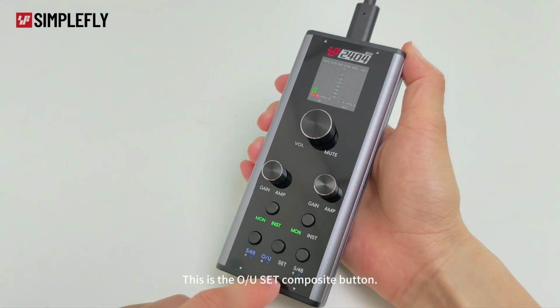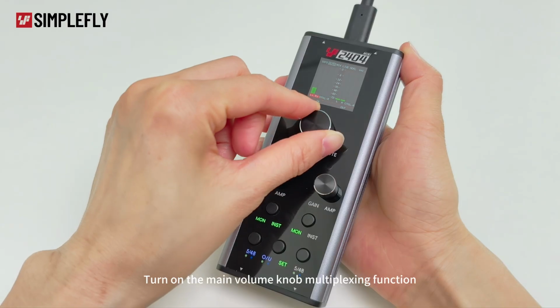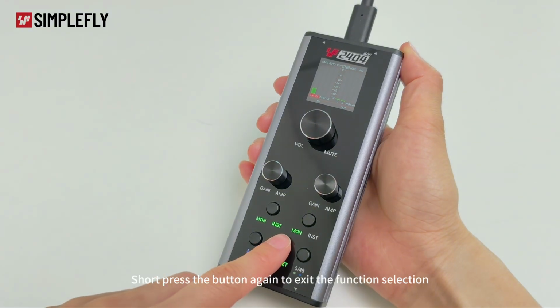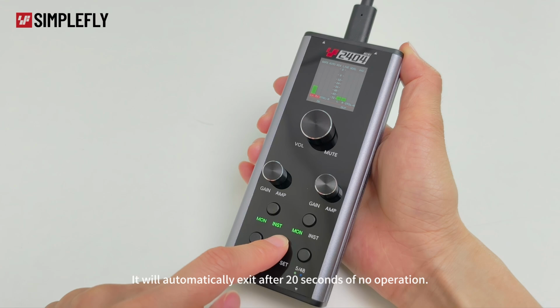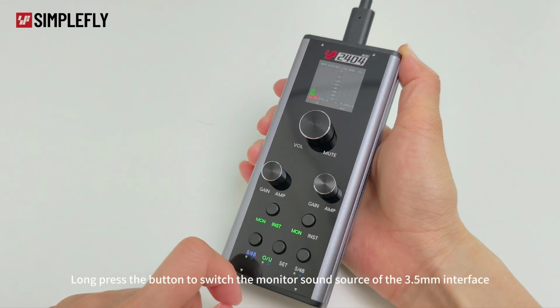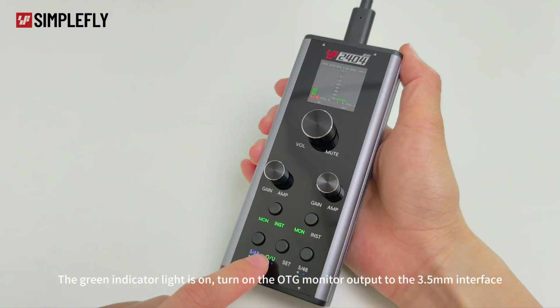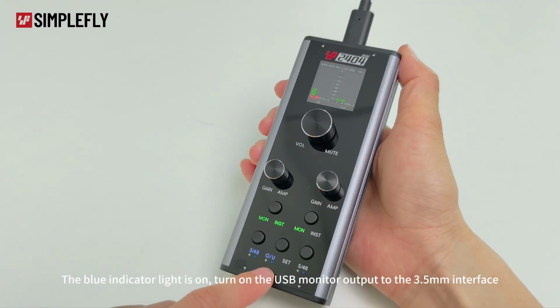This is the AUX or USB SET composite button. Short press the button, the SET indicator light is on, turning on the main volume knob multiplexing function. Short press the button again to exit the function selection. It enters the screen interface function selection and will automatically exit after 20 seconds of no operation. Long press the button to switch the monitor sound source of the 3.5mm interface. The green indicator light is on: OTG monitor output to the 3.5mm interface. The blue indicator light is on: USB monitor output to the 3.5mm interface.